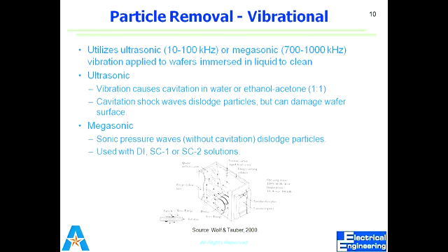The liquid that is used may be DI water, SC1 or SC2, the standard clean 1 and standard clean 2, which are parts of the RCA process. So it may be any chemical solution, and after that you give some higher waves than the ultrasonic waves, named the megasonic.